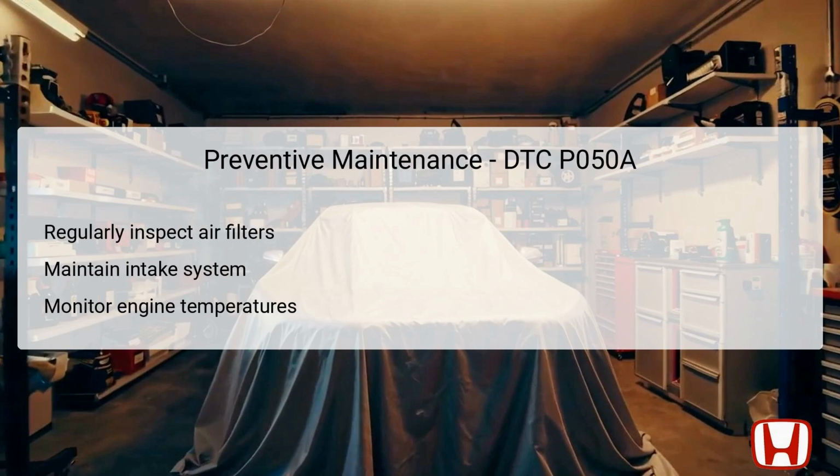To prevent issues related to DTC P050A in the future, it's essential to conduct regular maintenance of the air intake system and associated components. This includes routinely inspecting and replacing air filters to ensure clean airflow to the engine. Maintaining a clear and properly functioning intake system directly correlates with engine performance during cold starts.